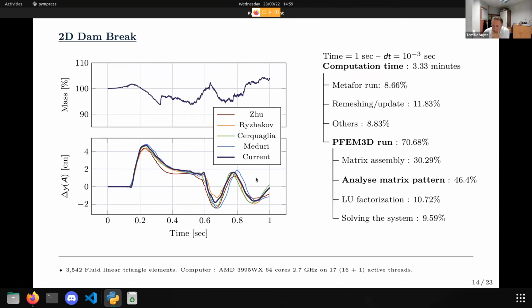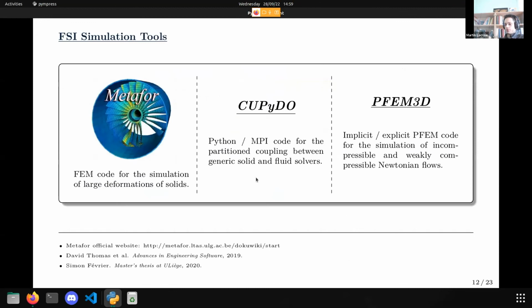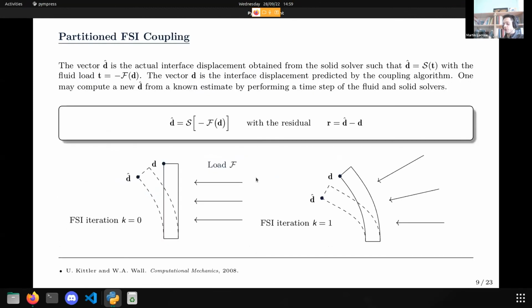Okay, thank you. So another question that's come in from Nassar. How does the remeshing affect the convergence? So that depends on the convergence that you are talking about. If I take the convergence in terms of fluid-structure interaction, because this is really the topic on which I'm working, so this residual here, if you compute a load of your fluid on your solid, and then you remesh, and you recompute the load without changing anything else, you will also affect this load a bit.